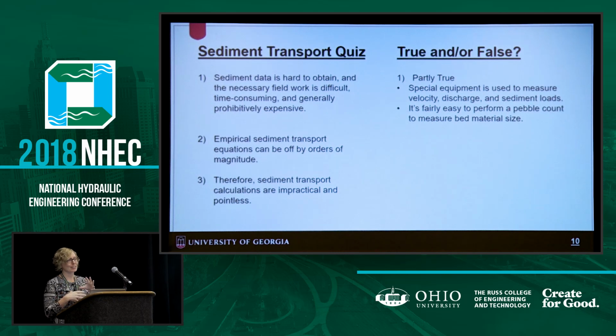So it's true, you need special field conditions and special equipment in order to measure your velocity, your discharge, and your sediment loads to actually know how much sediment is coming to you. But on the other hand, it's actually really easy to perform a pebble count to measure material size, which is used for sediment transport calculations.